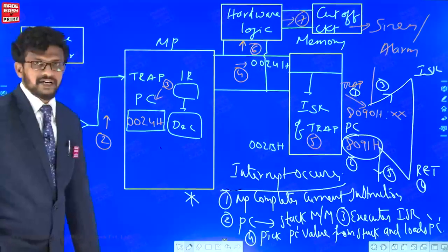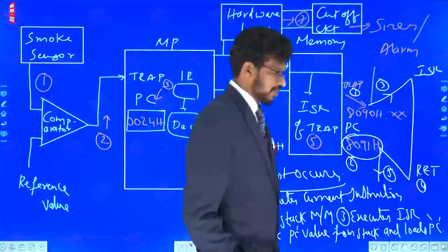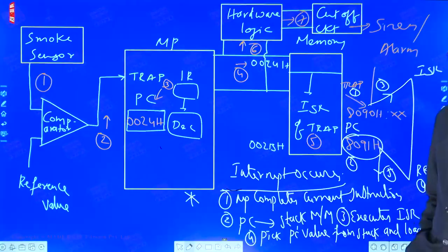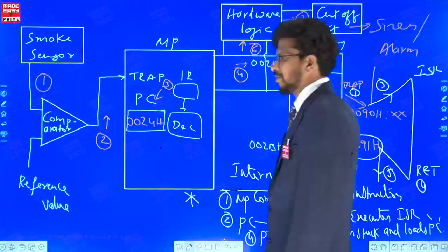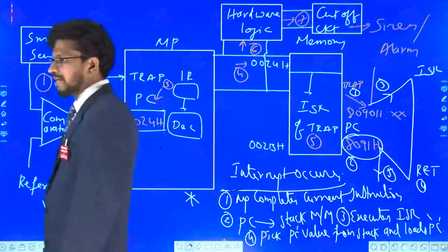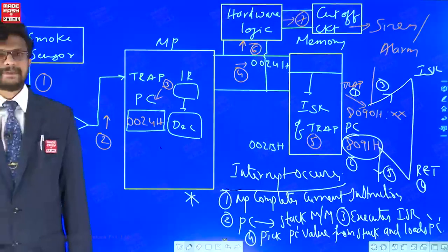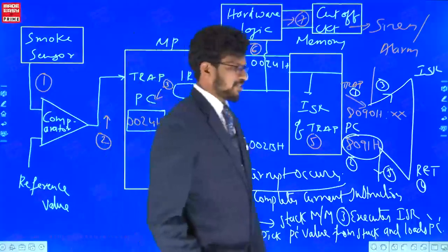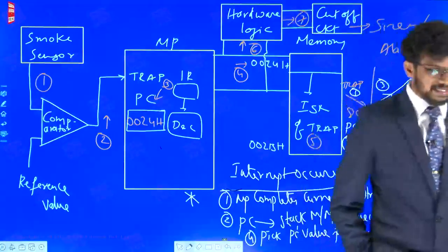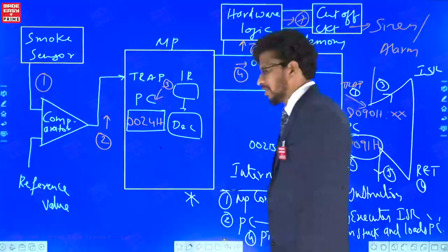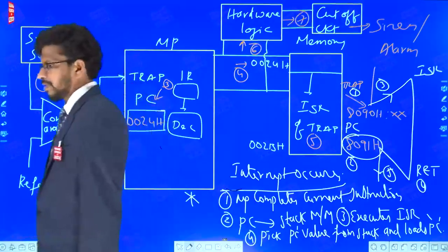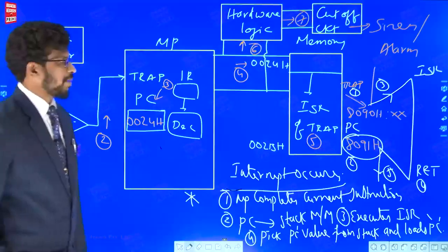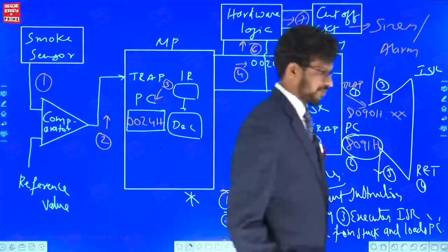If the length of the ISR or application program of the interrupt is more than the predefined bytes, an unconditional jump instruction can be used such that the program may be continued further.